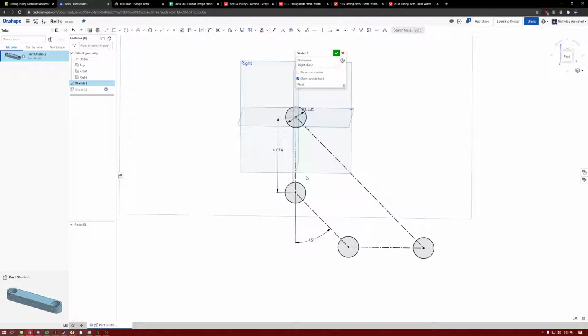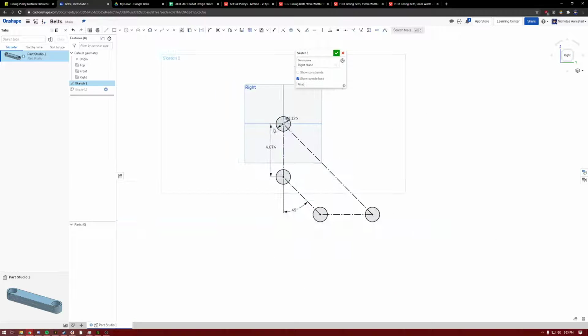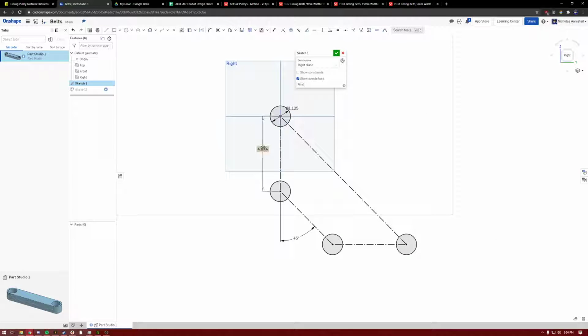What that does is reduce tension on the belt, which has some great benefits as far as reducing current draw on the mechanism. It might increase skipping, but on stuff like intakes, that's often not a big deal. So I'll pretty frequently find myself reducing somewhere in that 0.03, like a 32nd, to a 16th of an inch, right?